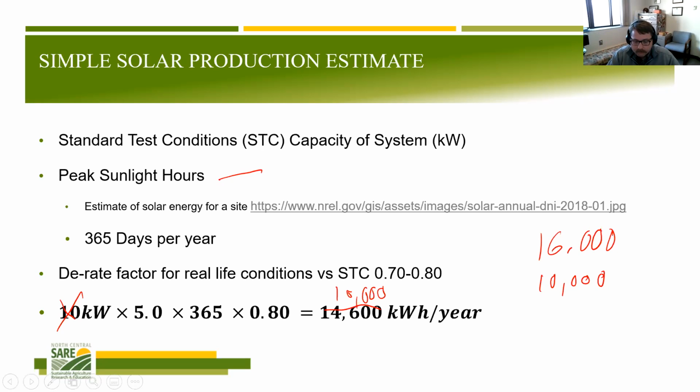Good question. One more question based on this screen here. Based on the discussion we just had around estimating what size system you would need for your home, how much area is required for a 300 watt panel? So you could add another layer to your calculations there based on the square footage per panel. Yeah, you could. A solar panel is about 5.5 feet by about 3 feet. That's very rough, but you could get a more detailed version. So about 16 square feet approximately is what each solar panel is.